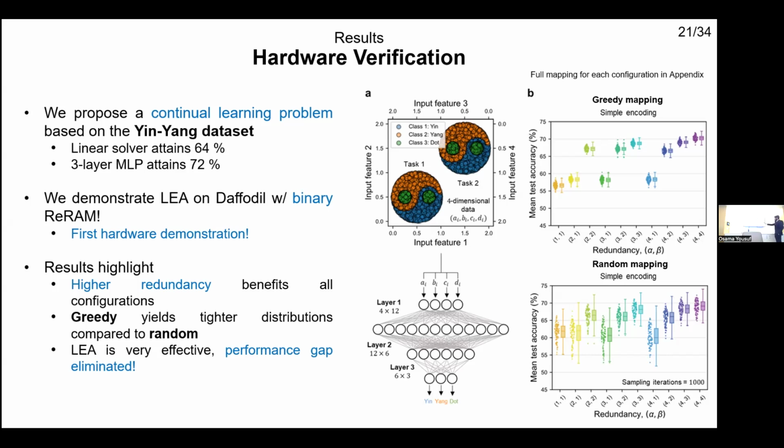And so towards the right here, I have on the x-axis, we have redundancy levels. I want you to focus on these 4 data points at alpha equals 4. What this is showing is that for the given network that we've already trained, if you were to deploy it on defective crossbars on the actual hardware prototyping platform, increasing the level of redundancy, or increasing the number of rows that you considered for averaging, directly corresponds to increments in your network's performance.